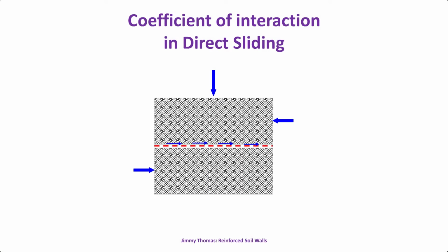So we have the shear box test actually. Normally, to determine the angle of friction of soil, we do the shear box test. Here the difference is we put the reinforcement at the interface. This is fixed, this is fixed, this is moving. So there is relative movement between the reinforcement and the soil. From that we can get the interface friction angle.